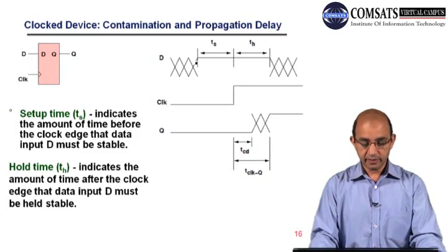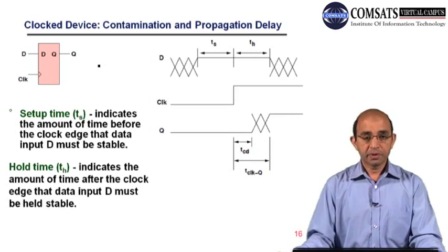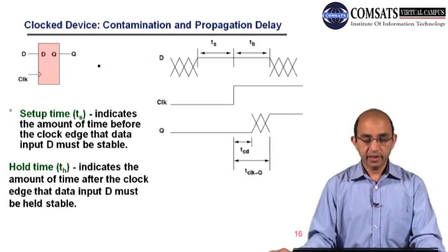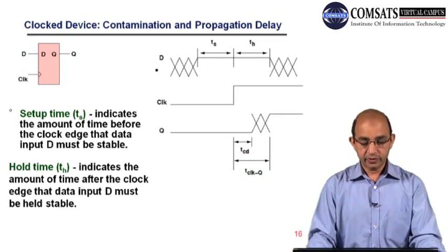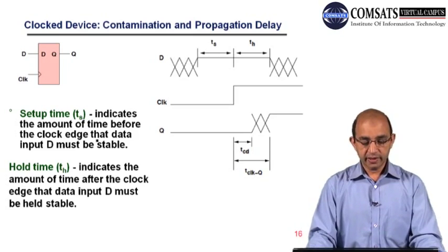So here you can see that we have defined some other parameters, and these are the setup time. The setup time, indicated by TS, indicates the amount of time before the clock edge that the data input must be stable.